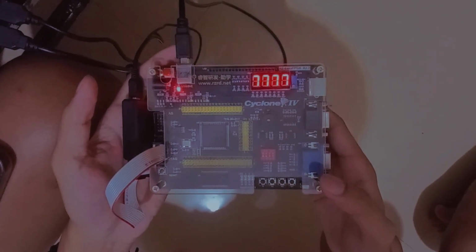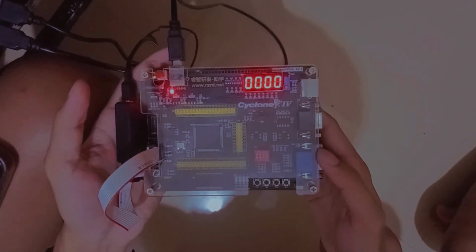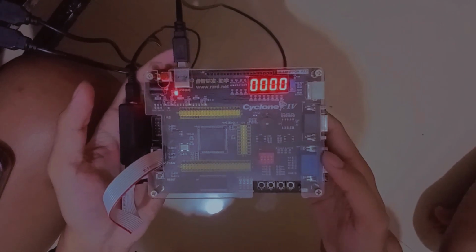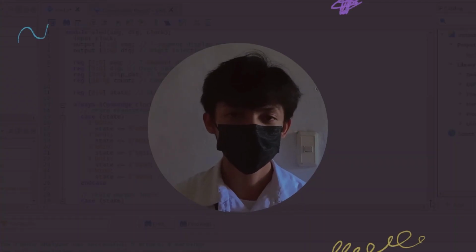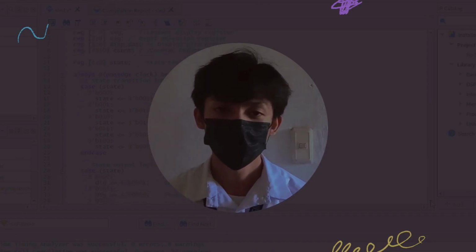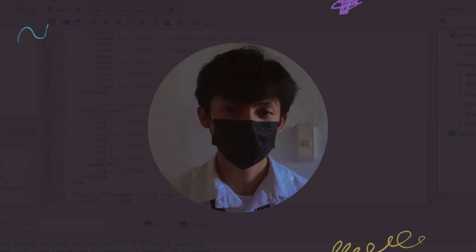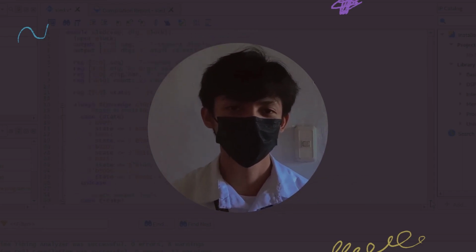By programming the FPGA with this code, the circuit can control the 7-segment display by sequentially enabling different digits and setting the appropriate segments to display the desired information. Overall, the FPGA is programmed to implement the sequential circuit described in the code, allowing it to control the 7-segment display based on the internal state and counter value, synchronized with the clock signal.